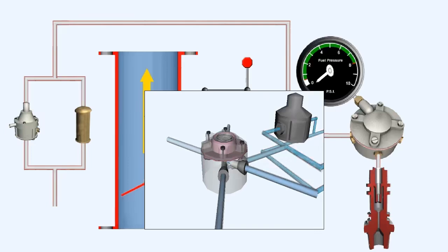When the inlet fuel pressure drops below a certain level, for instance at engine shutdown, the diaphragm closes the fuel inlet, which shuts off all the fuel to the discharge nozzles. This stops both vapour locks occurring in the delivery line and the engine running on when idle cutoff is selected. At the same time, it ensures that fuel pressure is available instantly the next time the engine is started.